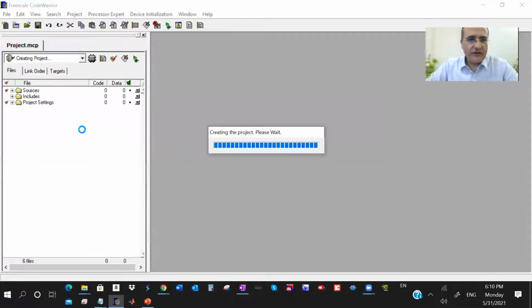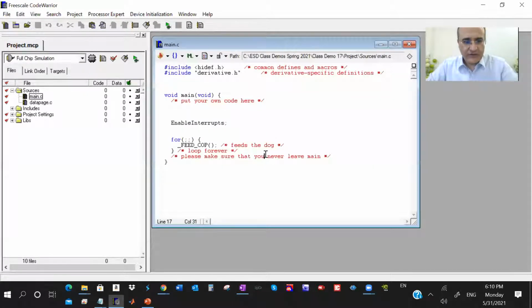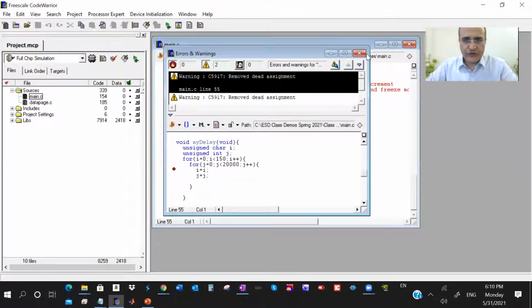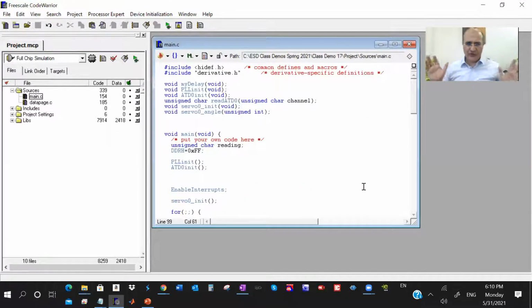Here the math is a little different. I use different values for the clock. Let's just make sure there are no problems. Okay, yeah. So here, guys, the same thing. I want to initialize the PWM, but in the 16-bit mode to be able to count more than 255, and then change the value of the pulse width to change the angle of the servo motor.